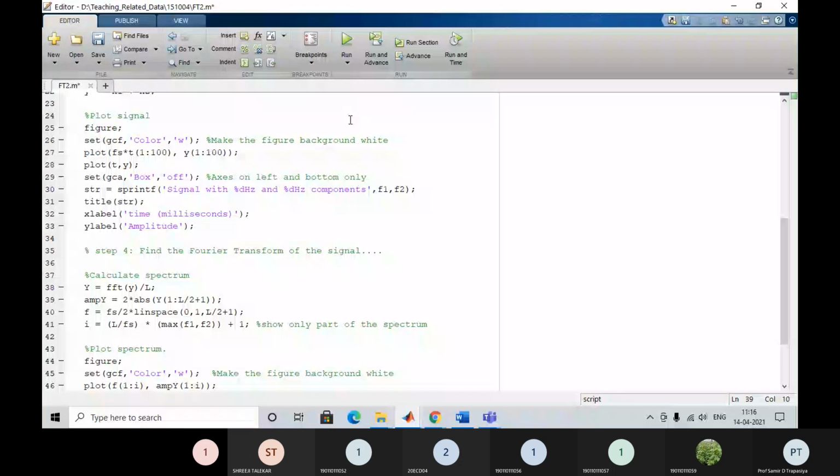Now in this program, we are not interested in plotting the negative parts of the spectrum, because the negative parts exist only because of symmetry in mathematics. But in real terms, if we observe the signal using a spectrum analyzer, the frequency is never negative. So we observe only the right side, the positive portion of the spectrum, and that's why we have to consider only half the points, not all of them.